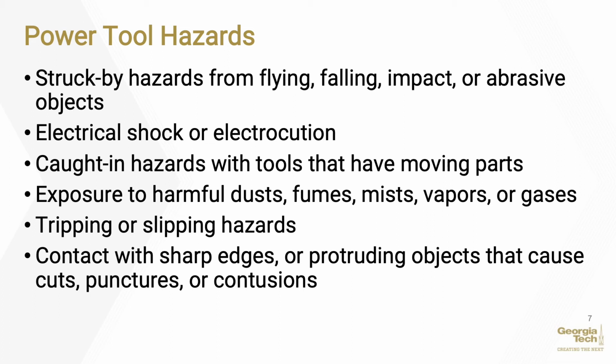Exposure to hazards can occur when a worker is using the wrong tool for the job, using a tool the wrong way, using damaged or broken tools, using tools that are dull, using spark-producing tools near flammable sources, using power tools with moving parts that are not properly guarded, using electrical tools that are not properly grounded, or not wearing appropriate PPE. Never carry a tool by the cord or hose.